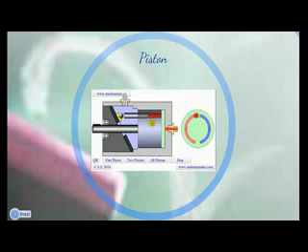Notice that for the high-pressured oil, the pistons move toward the port plate and force the hydraulic oil into the red crescent gap on the port plate. The movement of the oil in the crescents is shown with the white bubbles. For high-pressured oil, the bubbles move toward the exit port, indicating that the oil is coming from the cylinders. For low-pressured oil, the bubbles move away from the inlet port, indicating that the oil is coming from the outside. The oil in the blue crescent is sucked in by the pistons moving away from the port plate.